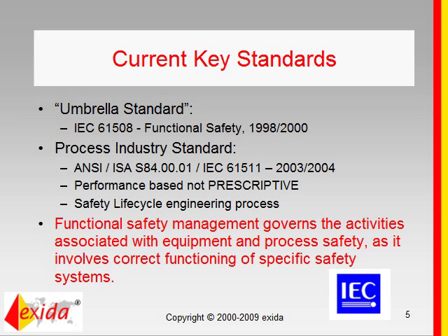In the process industry, IEC 61511 is the international derivative. In the US, there is the ANSI/ISA 84.00.01-2004, which is a variation of IEC 61511 in that it has some explanatory text in addition to a grandfather clause. One of the key things to remember is that these are performance-based standards, not prescriptive, meaning that you can do whatever you want as long as you can demonstrate that you meet your performance criteria. At the same time, a negative is that there are no prescriptive rules telling you what to do.